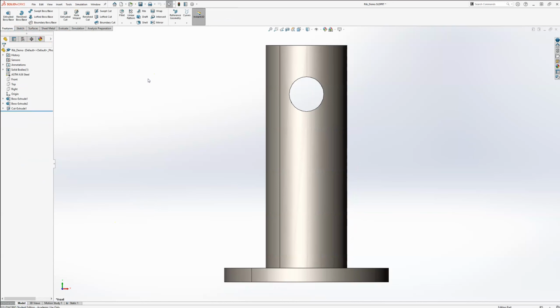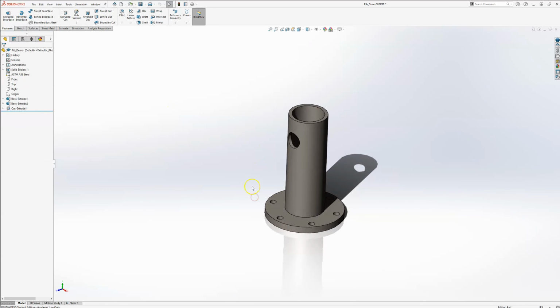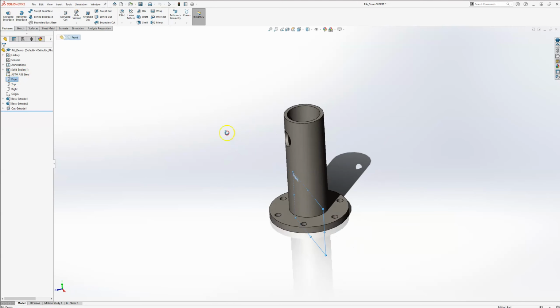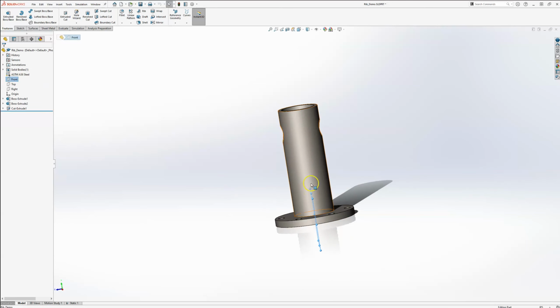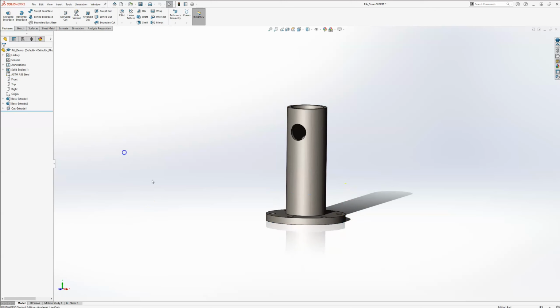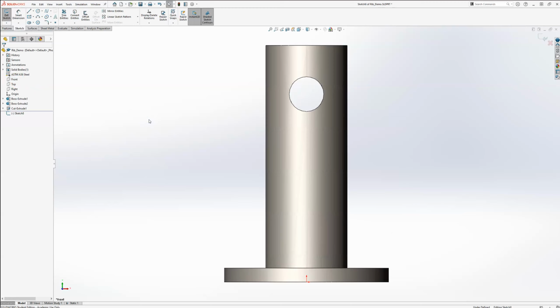And so to make this rib feature, first I need to think of what plane I'm going to make my initial sketch on. In this case, the front plane is placed appropriately. I'm going to have it basically where the rib is sitting right in the middle of the part in that front plane. So I'll just go ahead and create a nice two-dimensional sketch on the front plane.